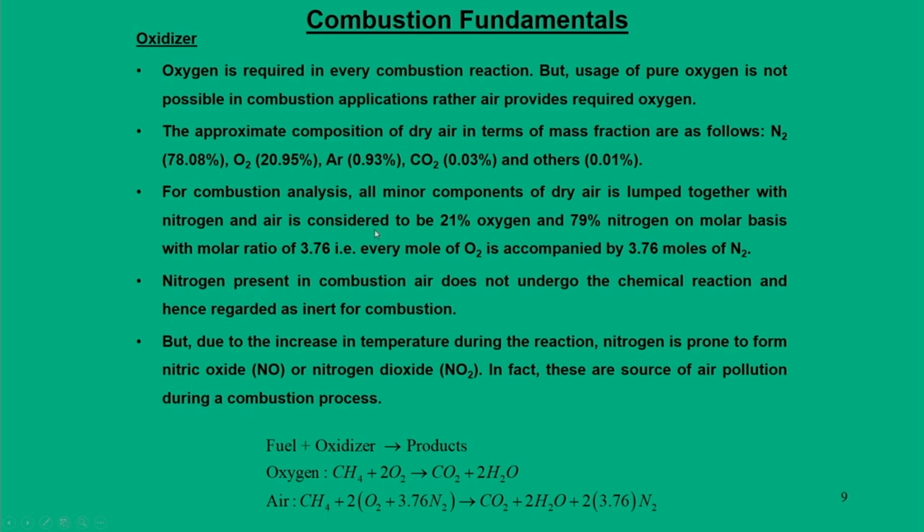So for combustion analysis, we say air consists of nitrogen and oxygen, containing 21% oxygen and 79% nitrogen on a molar basis, with a molar ratio of 3.76, which means 1 mole of oxygen from air is always accompanied by 3.76 moles of nitrogen.